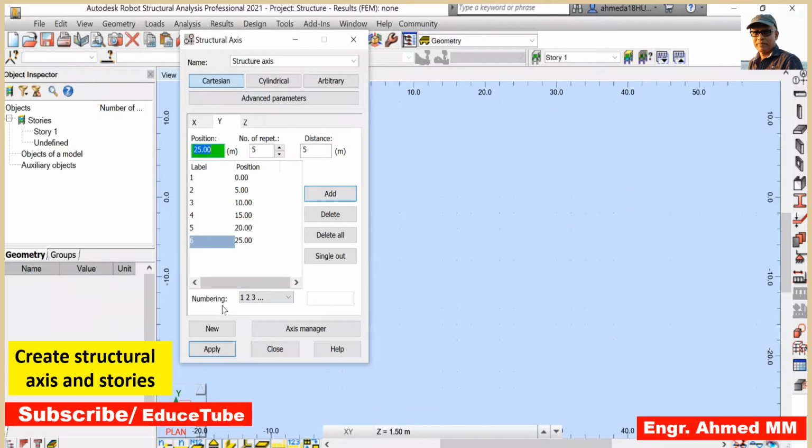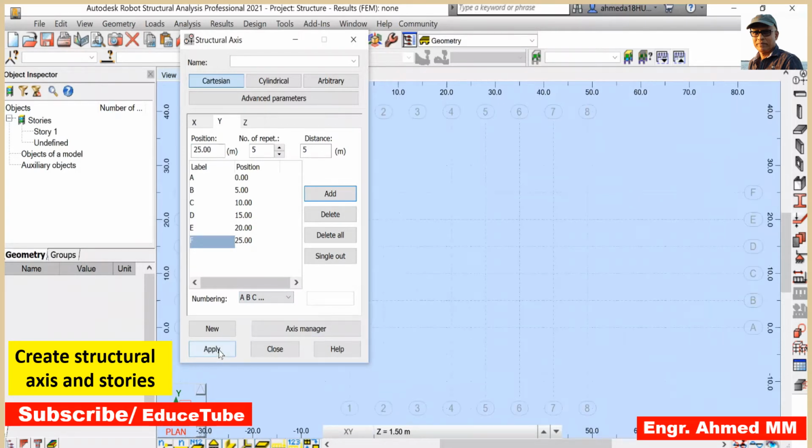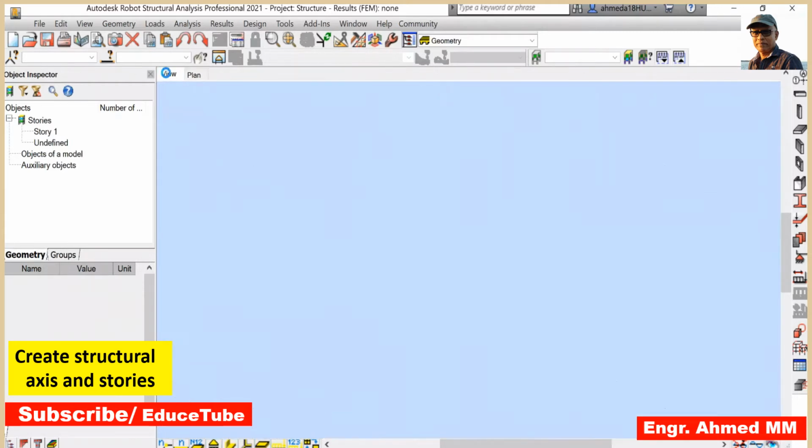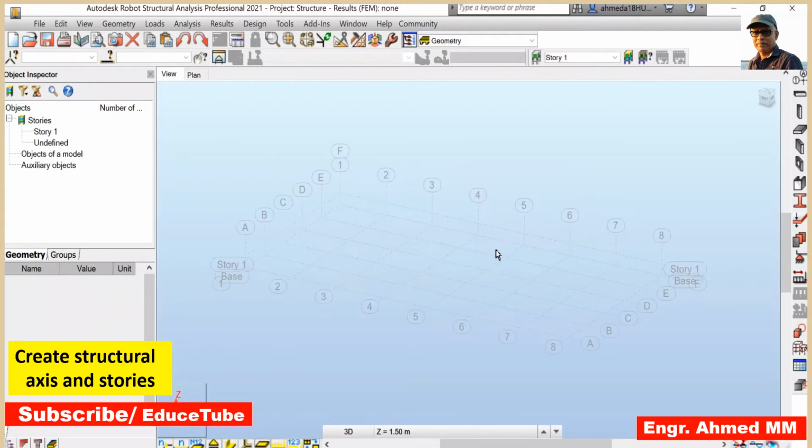Here I need to change numbers. For the X tab it was 1 to 3, but for the Y tab it must be different, say A, B, C. Apply it. Close this. So we got the axis. Let's see in view how it looks. This is the thing.